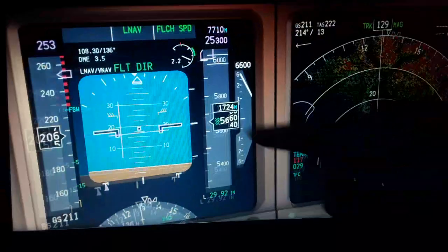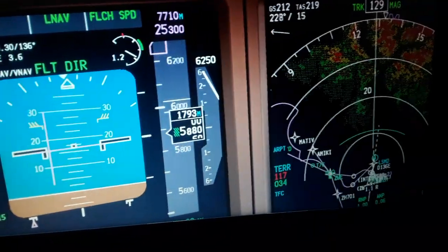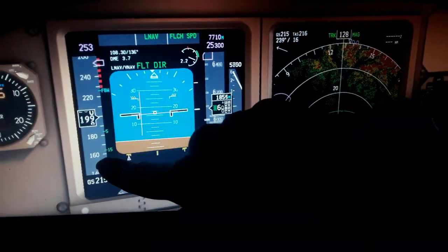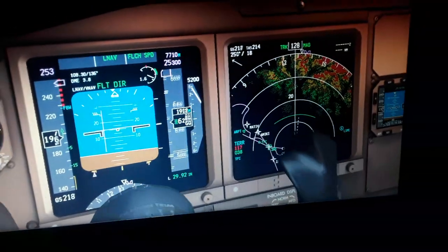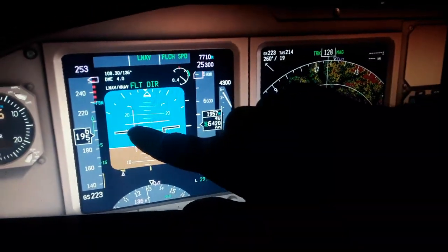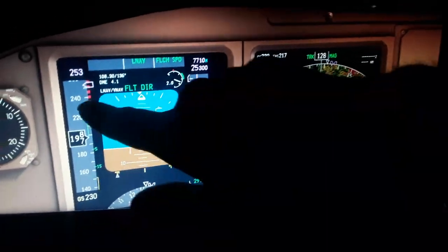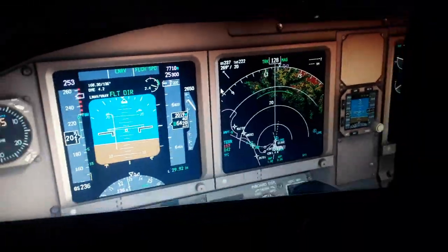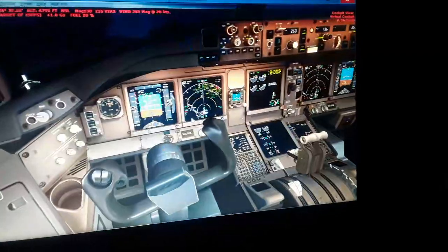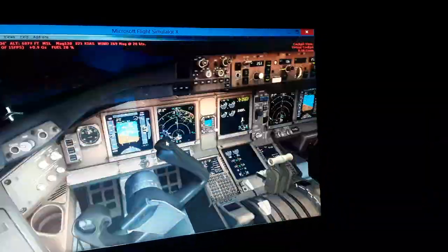So you can see we have the climb here, the rate of climb, the airspeed, the stall speed is here. We need to avoid the stall speed, so we pitch down the aircraft and increase the airspeed. Also here the flap warning. So this is after takeoff. Now we start making the turn.